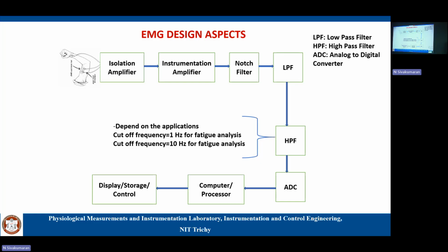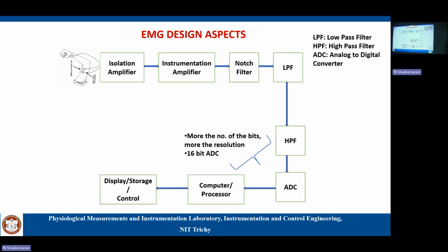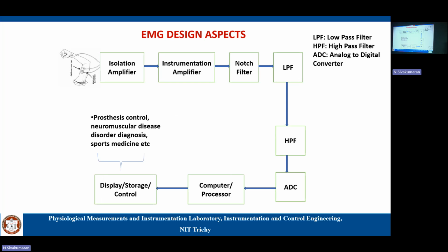So first we start with anti-aliasing, so that we ensure the signal we have in hand falls in the desired range. Technically it should be twice the maximum frequency, but if you practically try to implement it, generally we choose 4 times, 5 times the maximum frequency. Next, the number of bits. I'll come to that. Anyway, this is too technical. Okay, next.